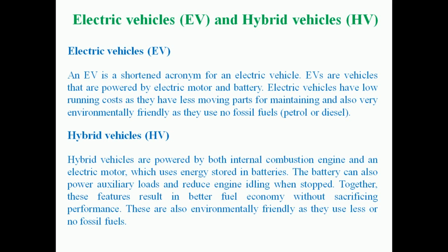During that time, the torque at the shaft of the internal combustion engine is used for the generator to generate electricity. The electricity generated is supplied to charge the batteries. In turn, whenever necessary, we can use the power from the batteries to run the vehicle. Whenever necessary we can use power from one system, and whenever necessary we can switch to the other power. Like that, this is the hybrid vehicle.